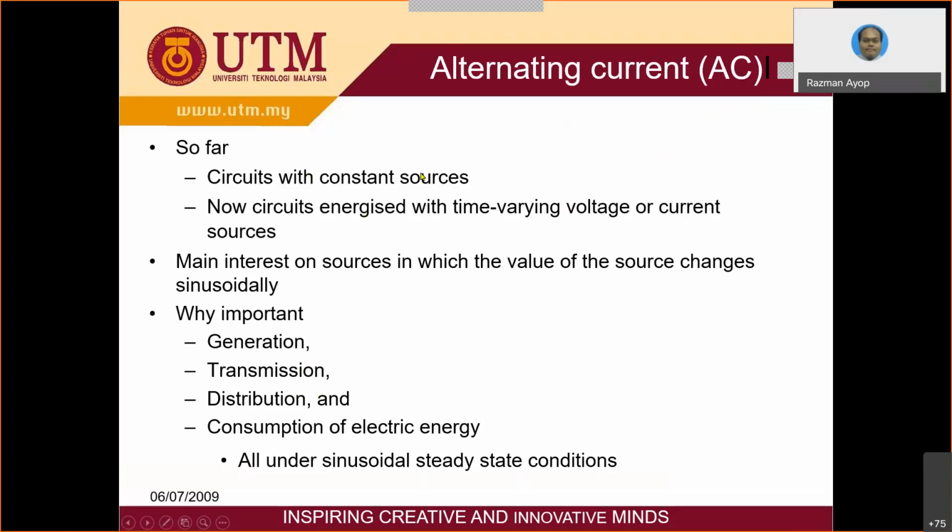Because of power loss. In the wire there is power loss, so P equals I squared R, where R means the resistance in the wire. In the transmission wire, the resistance is not too high, but there is resistance. So in order to reduce the power loss, we use a lower current. That's why we increase the voltage, to reduce the current.